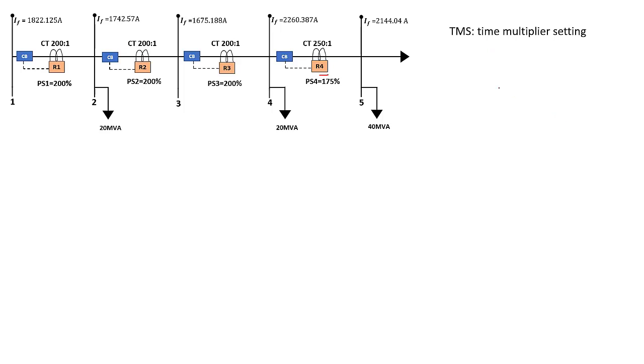The other important factor is obviously TA, the actual tripping time at which your IDMT relay is supposed to trip. And then we also have TC, that is the operating time. So you have TA and TC. And then the last element is the multiple of current setting, or multiple of setting current. You have to keep these elements in mind, and you need to understand what they are if you want to understand how to calculate the IDMT relays' tripping time. Again, you can watch that tutorial I did on the IDMT relay to get some further understanding.